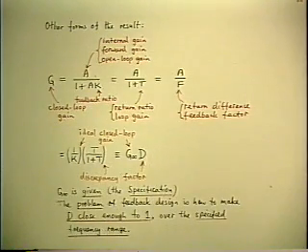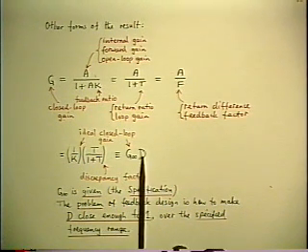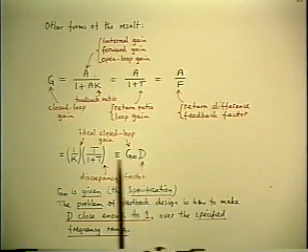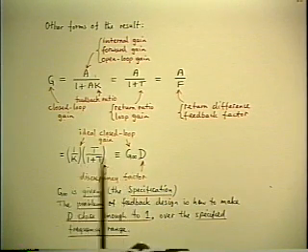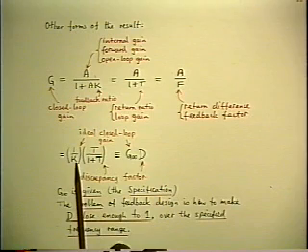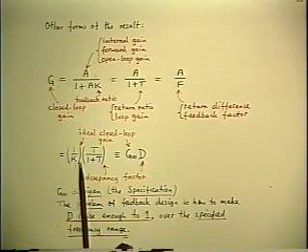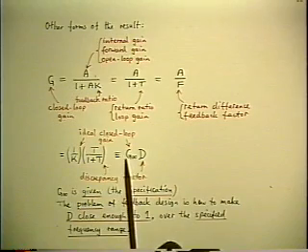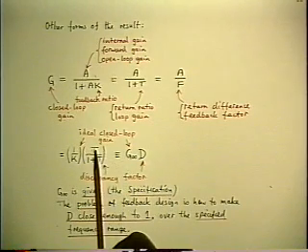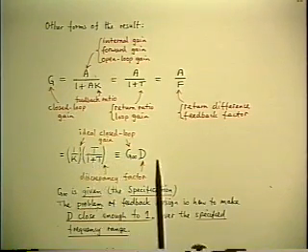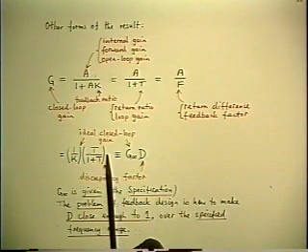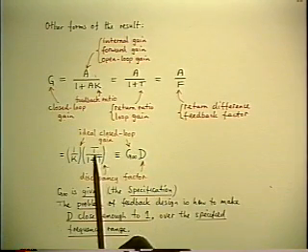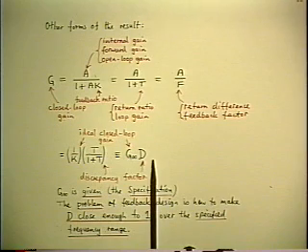So the hard part of designing a feedback amplifier resides in only one of the three requirements. The first requirement is you make G infinity what it needs to be, which means you design the feedback path independently to get the required G infinity. That's easy. The second requirement is you make t very big. That's easy. The only hard part is making t big over a wide enough frequency range.